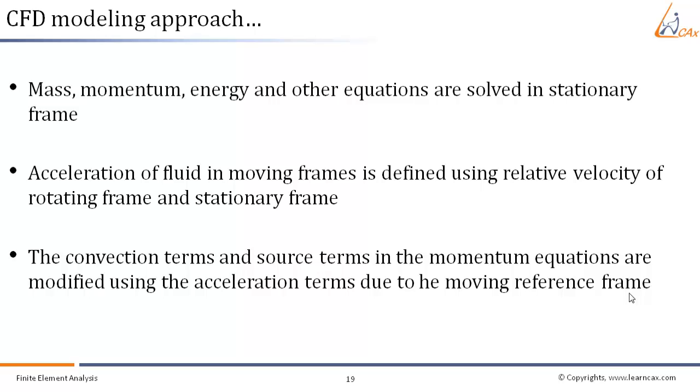The original momentum equation is then modified using the acceleration term, which is obtained because of the moving reference frame. So that is how the effect of rotation is included even in steady state equations.